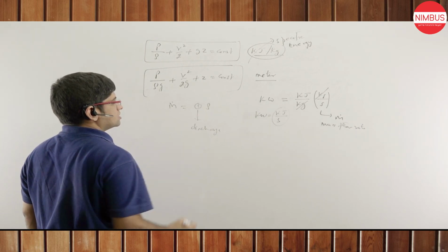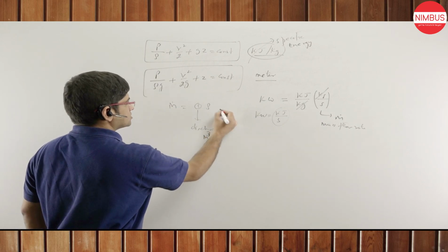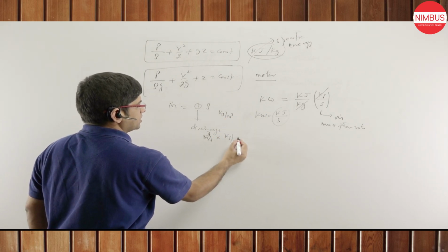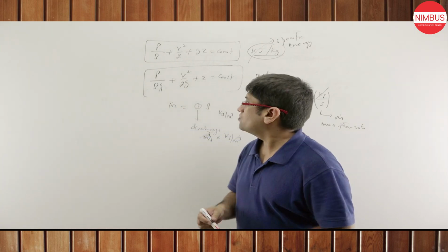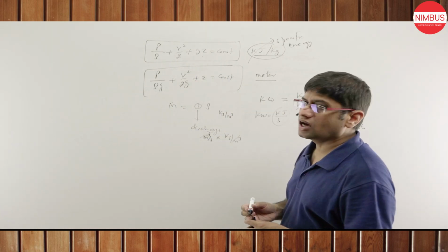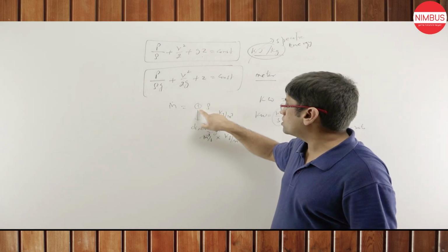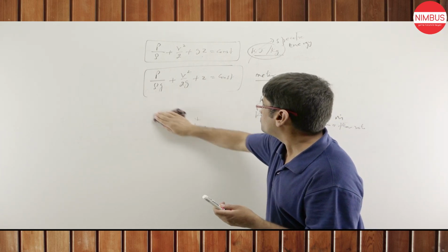So sir, density into discharge. Discharge is meter cube per second and density is kilogram per meter cube. So if I multiply kilogram per meter cube with meter cube per second, I get mass flow rate. That means if I multiply this equation with mass flow rate, with rho into q, rho q is discharge, volume flow rate, then I get equation in the power terms.